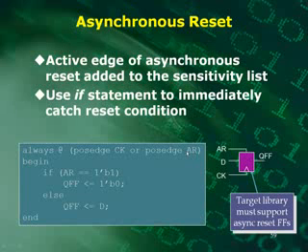You can do this. Be very careful with asynchronous resets. You can violate setups and holds. Maybe I should post a good paper that somebody wrote on this. What can happen is when you release the asynchronous reset with respect to the clock, you can violate hold conditions, and that would produce problems on your output. I probably need to put up a paper for you to read about that.